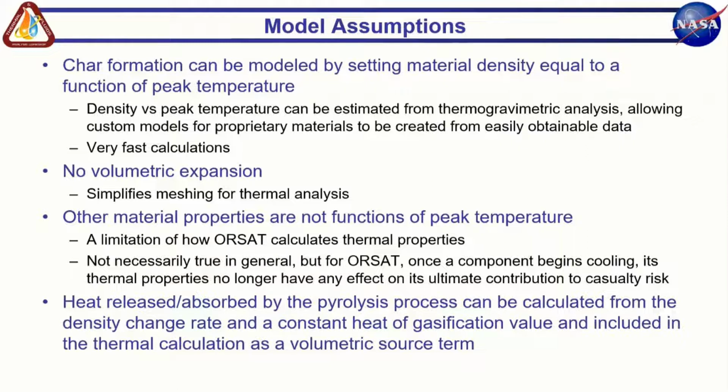We also assume there is no volumetric expansion. So you saw in one of the previous slides that this is not strictly speaking true, but it is a limitation of how ORSAT meshes the components. And the other material properties are not functions of peak temperature, they're only functions of current temperature. This is a limitation of how ORSAT calculates thermal properties.